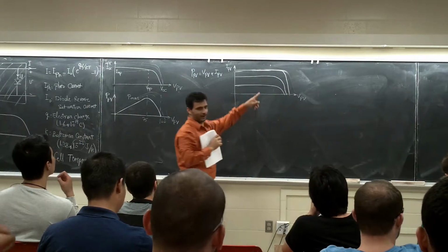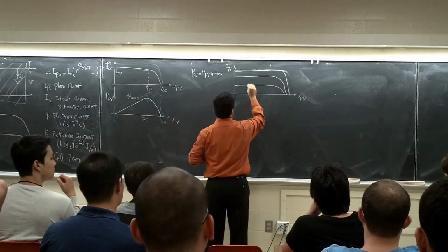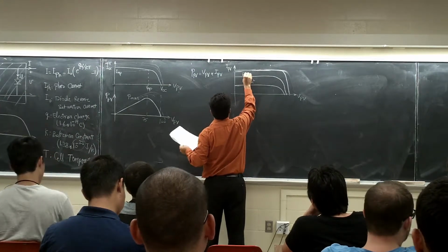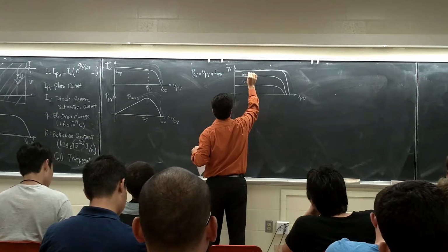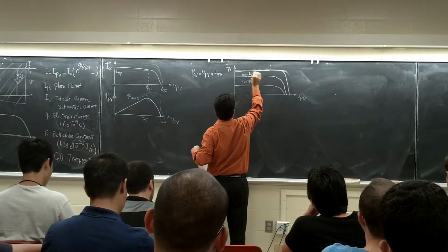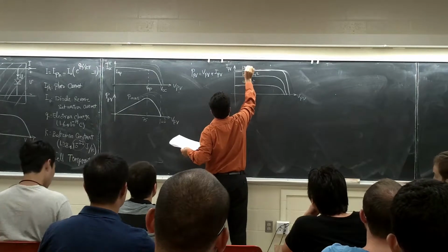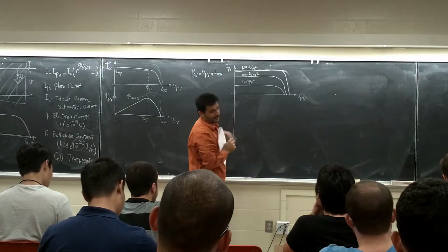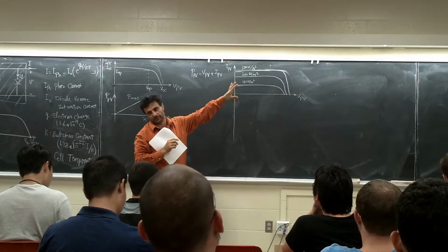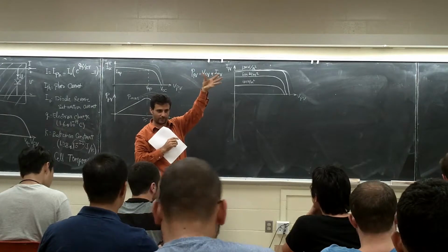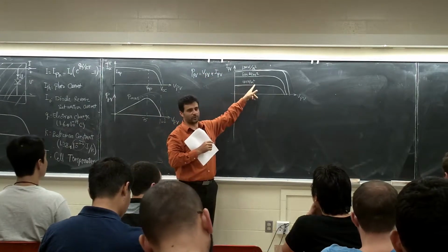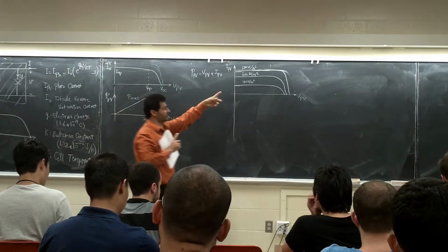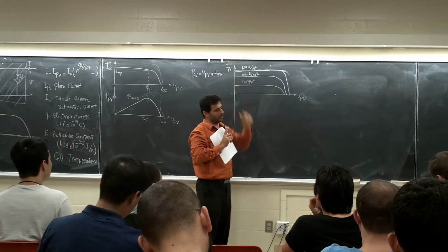So you can see here, for example, this is 400 watt per square meter. This is 600 watt per square meter. And this is, for example, 1000 watt per square meter. They call this irradiance variation, based on how much sun energy is being used, because it is watt per square meter. If you have 1 square meter of solar panel, under this condition it is going to generate 400 watt, this one 600, and so on.